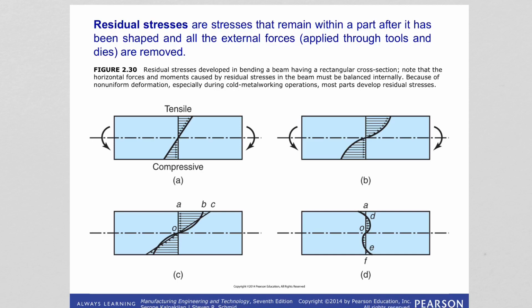And under bending, of course, there is a distribution of tensile and compressive stresses forming in this bar. At some point, these bending stresses will reach a point where the material is experiencing yielding, and the stress distribution will look like this.